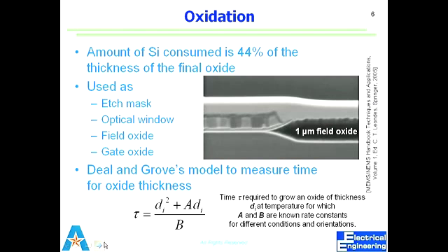So we use Teflon tweezers or Teflon coated tweezers. We use Teflon containers. We use Teflon wafer holders, like the one which we can use to dip it, right? So that's all part of the recipe. So you would know, okay, I have to etch silicon dioxide.